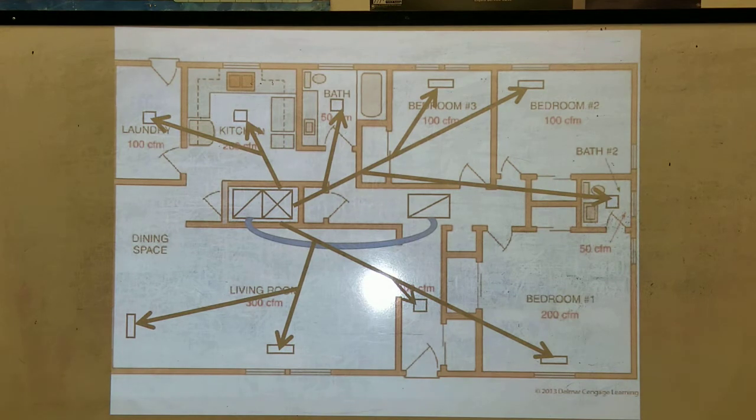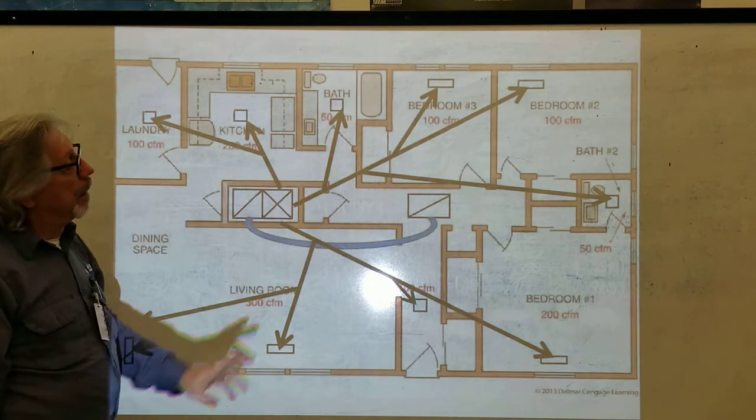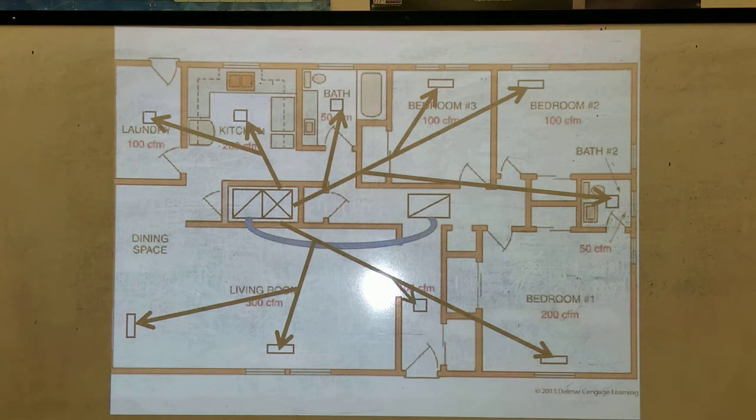So that's completed the ductwork, that's a layout, that's a pretty simple layout, and you make it as simple as possible, because you're gonna go as straight as possible, because moving air has inertia, meaning it wants to go in a straight line, so we're just making it go in a straight line, as straight as possible, right?